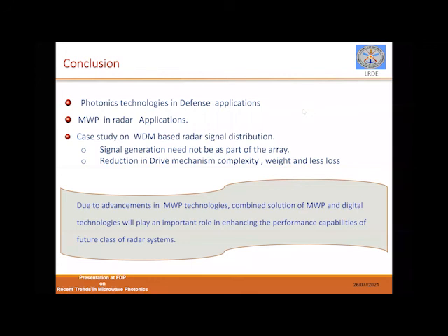Okay, ma'am. If I use that RF transmitter at the first stage, it is converted to optical. Once it is optical, that methodology is used only for transporting one RF, or multiple RF signals with digital or whatever it is, to another location using WDM technology. Where I was talking about signal generation and detection is a completely different process for up conversion, and no up conversion or down conversion is required in photonic methods. So don't get confused. If you read more, you will understand.